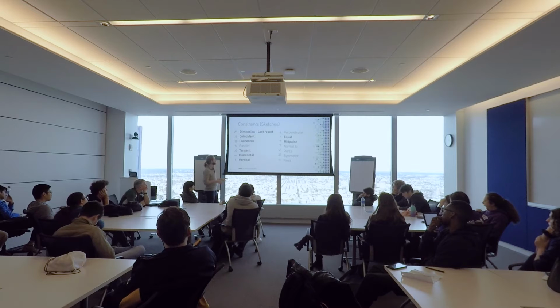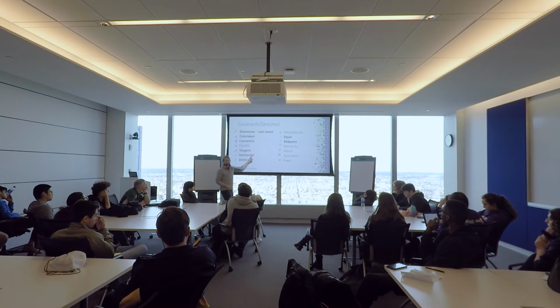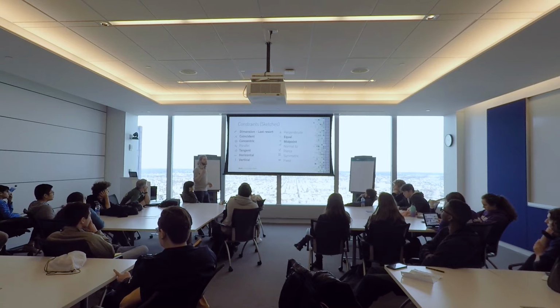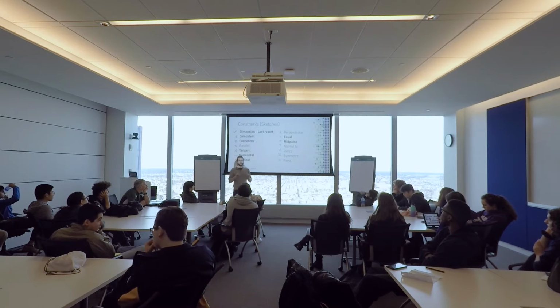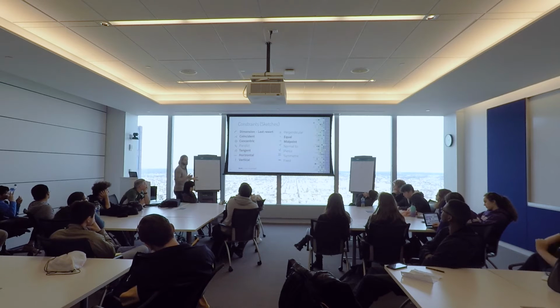But the two important ones that I want to point out that I use all the time that I don't see people using often are equal and midpoint. Equal is fantastically useful because you set one thing in one location with one dimension and you can set it equal to each other. Equal is a good way to set a bolt pattern as well. You draw a bunch of dots, you put lines between them, and you set all the lines between them equal. And then you know that that's a bolt pattern no matter what. You maybe just dimension one of the spacings and then they're all equal. And they can be automatically centered that way as well.